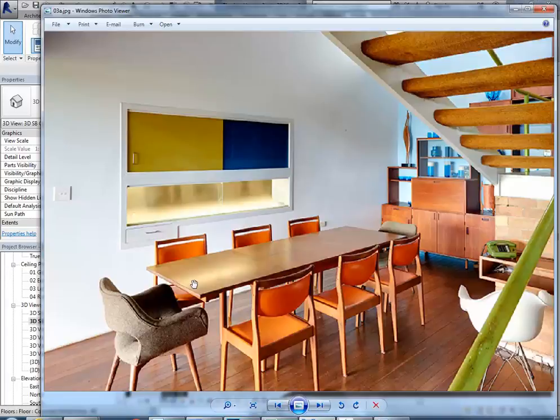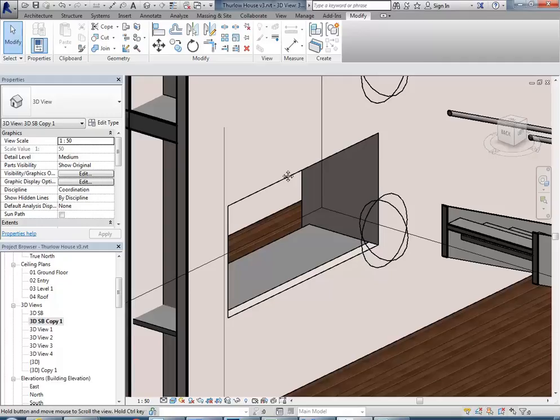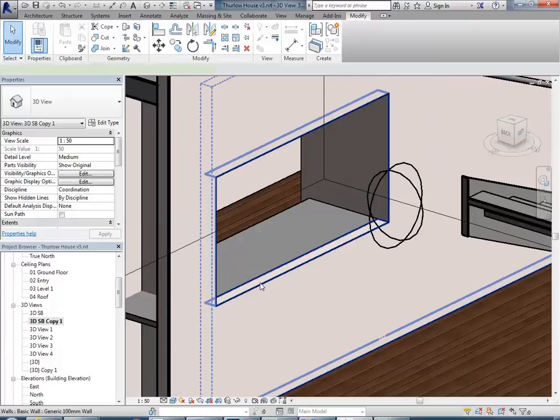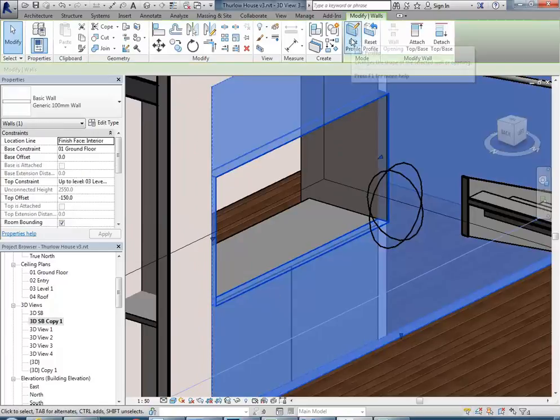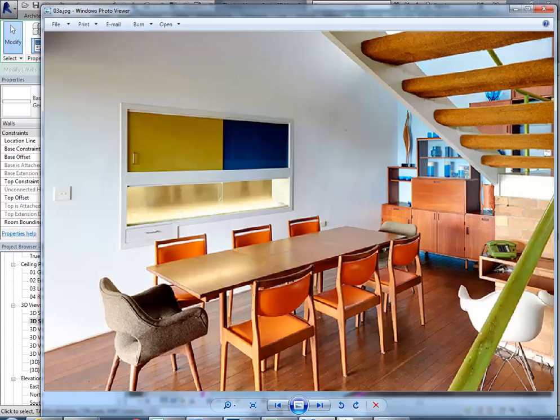Okay, so strictly speaking, the bench top there should be extended into the wall cavity, but I would just model, and if you want to put that detail in, it's a nice thing to try. So you could come back to that wall profile and edit profile again, and put in a cutout for that drawer.